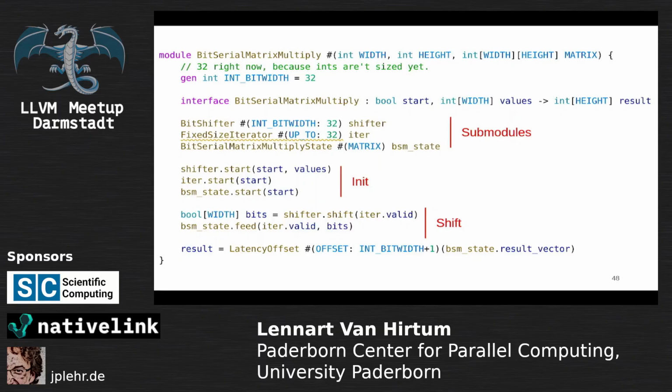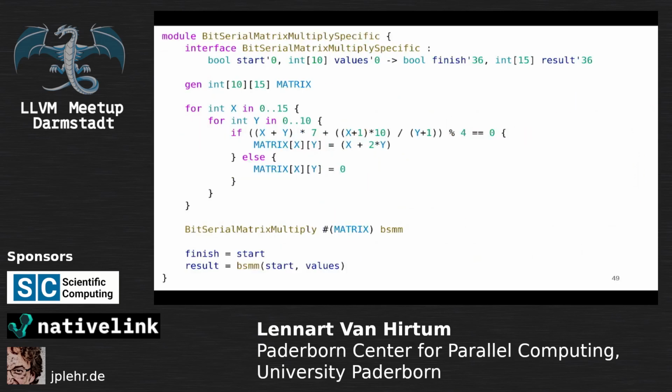And then at the end, this is again something curious. We are compensating for 33 cycles of processing by shifting the latency again, such that when I call this bit serial matrix multiply module and give it some input parameters, its output is shifted in latency by, I'm guessing in this case, about 36, so they will match. That way, in later hardware you can use this module transparently, without having to think, okay, this module takes 33 cycles. This might be the least intuitive part of the latency counting system, I give you that.